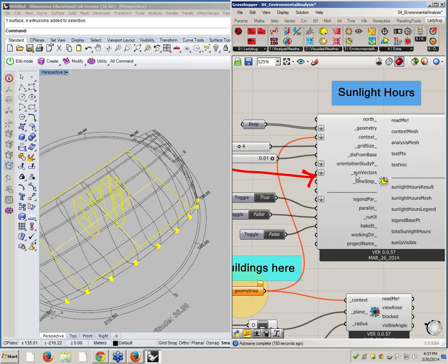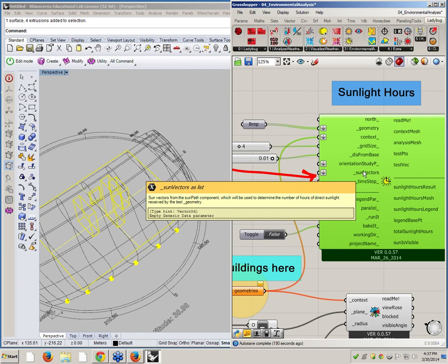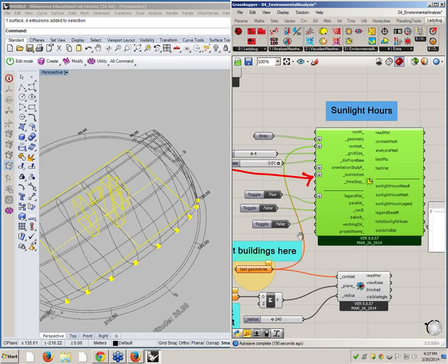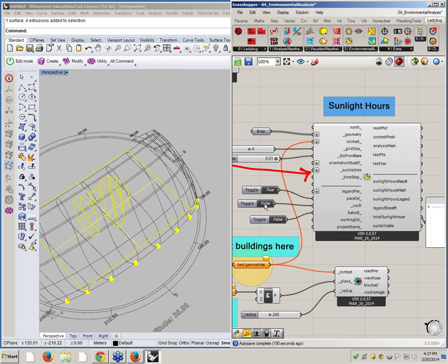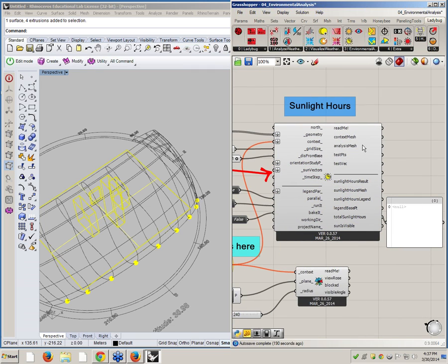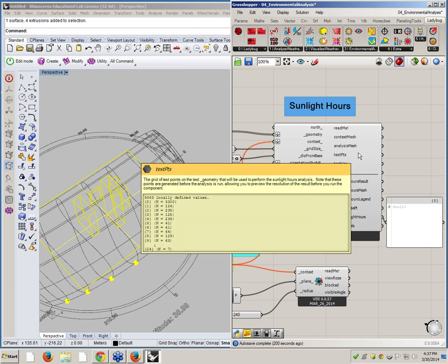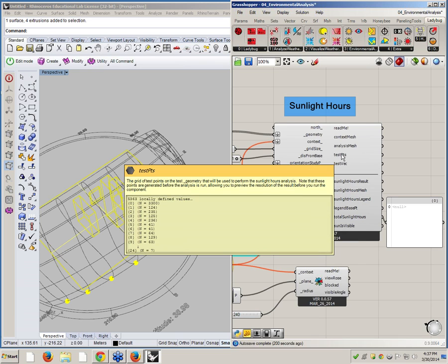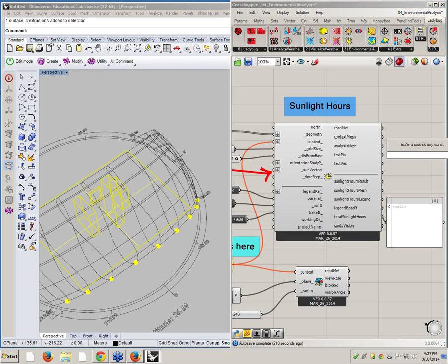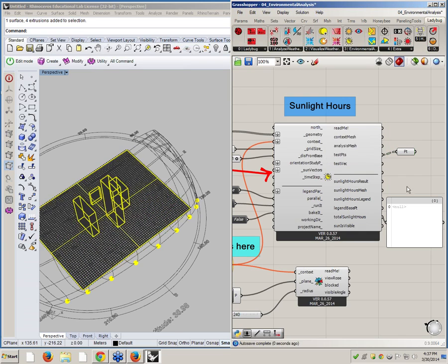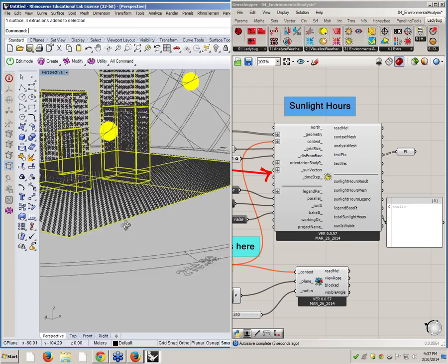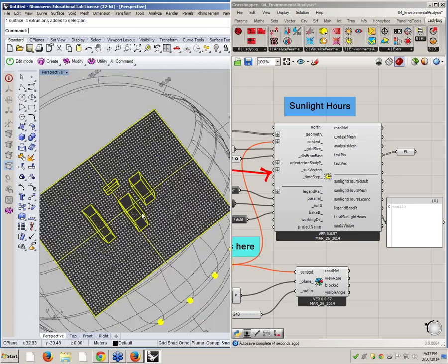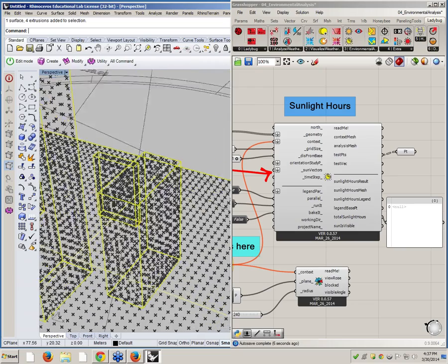If you don't connect the sun vector, and set run it to true, it does something. This is one of the other turbo buttons that is nowhere, but you should know. So there is an output for test points. If I type point and connect my outputs here, it shows me the test points. What's the use of this? It's so useful to check how dense your grid is.